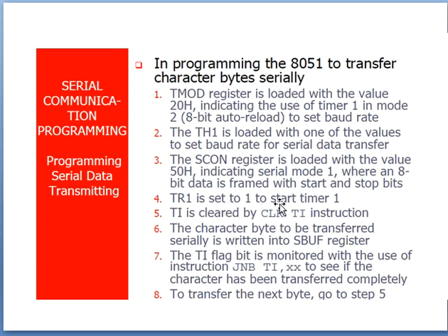Then TR1 is set to 1 to start the timer. We know we are using timer 1, so if you want to start the timer, we need to set TR1. We need to set the TR1 bit so that it can start the timer. If you want to stop the timer, you need to clear this TR1 bit.